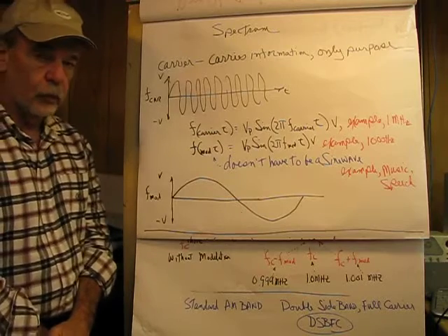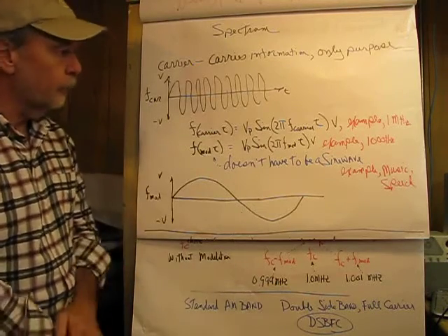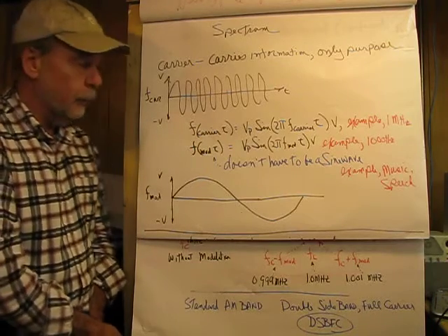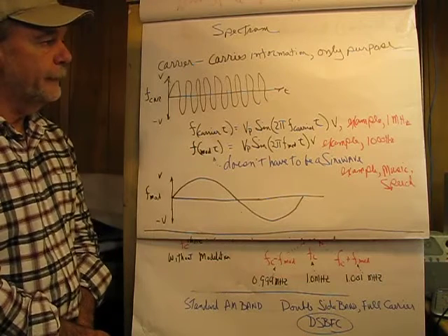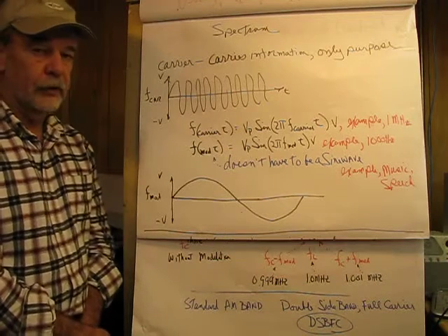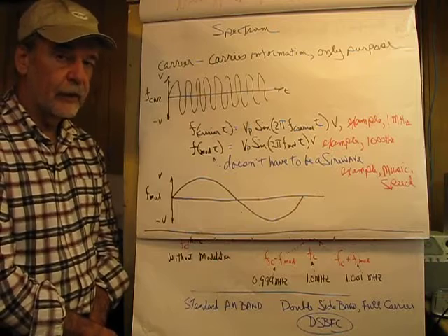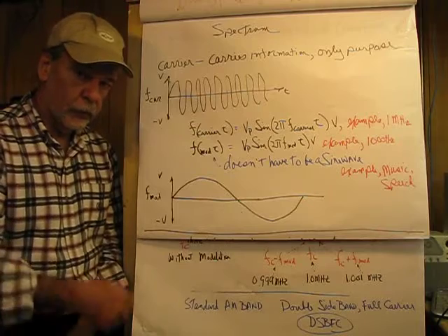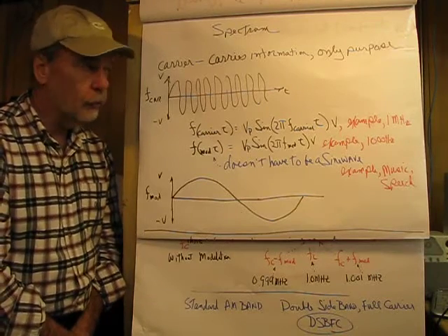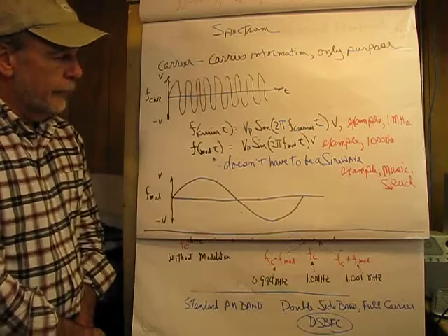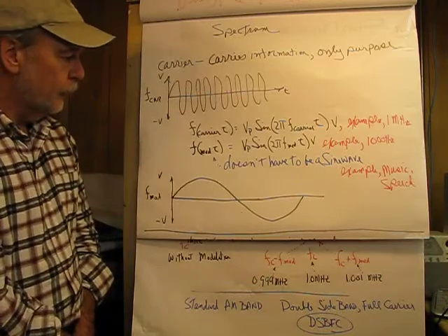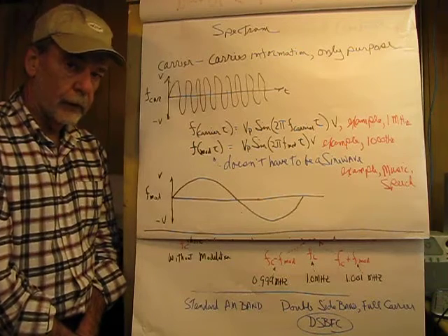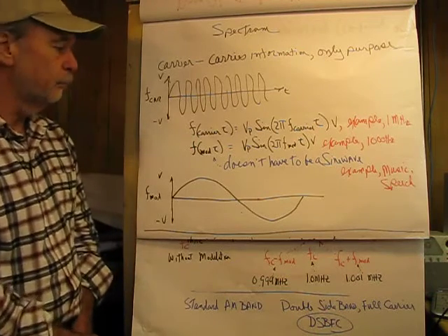And that's not the case with the AM we're going to be discussing from here forth, except for data transmissions at the very end. So we have a carrier, and the carrier carries the information, nothing more. It does not contain information, and other than that it's needed for decoding the signal with the receiver, it's basically useless. The reason it began in this manner is because the electronics back in the day weren't sophisticated enough to use any other type of modulation.